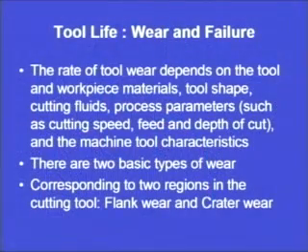So, the rate of tool wear depends on the parameters we have already seen. It depends upon the workpiece material and the tool material. Moreover, it depends upon the shape of the tool. Moreover, it depends upon the cutting fluids. Now, one important parameter that results in tool wear is the temperature, or the heat, that is generated during the cutting operation. In the cutting zone, where the tool is in direct contact with the workpiece and the temperature is rising, if we are able to supply the cutting fluid, the temperature will be lowered. Here the cutting fluid acts as a cooling agent.